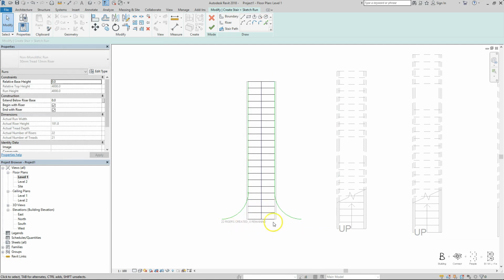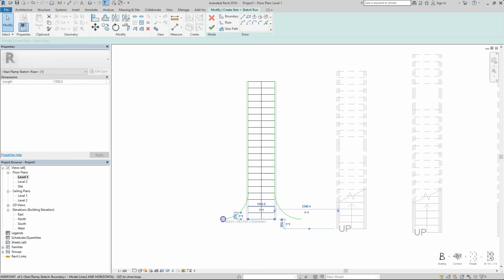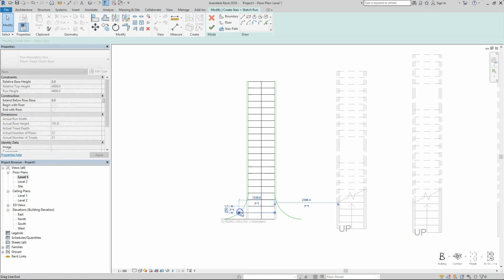Another criterion for a sketch to work is to have those risers. The risers are in black. As you can see, these riser buttons over here create the black lines on your sketches. So both ends of the riser must touch both ends of the boundary lines. So just click and drag to the side. And drag this one as well. It's just a little bit here.